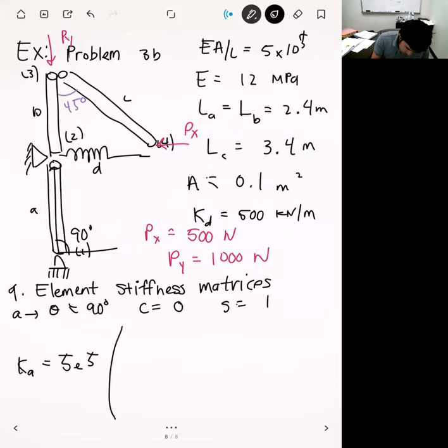And then the element stiffness matrix. Remember that the entire first row is zeros because those are all the cosine terms. And remember the other trick I taught you: because it's symmetric, you can build up the element stiffness matrix row by column. When you write the first row, you can assume that the first row is also the first column. Because we have 0, 0, 0, 0 in the first row, our first column is also 0, 0, 0, 0. Just like that.